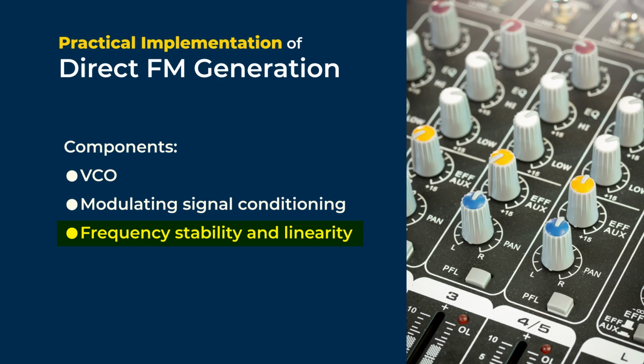Frequency stability and linearity are critical parameters in direct FM generation. The stability of the VCO's output frequency is influenced by factors such as temperature variation, power supply fluctuations, and component aging. To achieve high stability, temperature compensated or temperature controlled VCOs are often used.